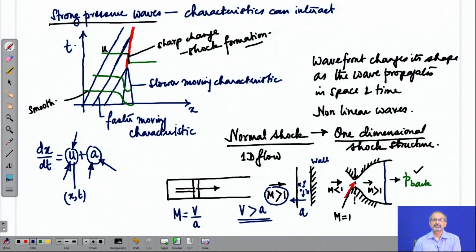So, what happens effectively is that though these molecular collisions are propagating upstream, trying to spread the information through these disturbances, they do not manage to go far upstream, because the incoming flow is higher than the sonic speed. The sonic speed is not sufficient for the disturbances to propagate far upstream, and therefore, at some point there is accumulation of disturbances forming the shock.